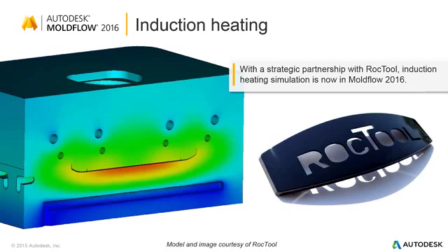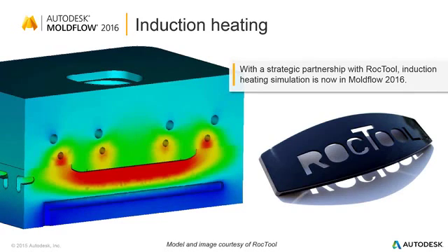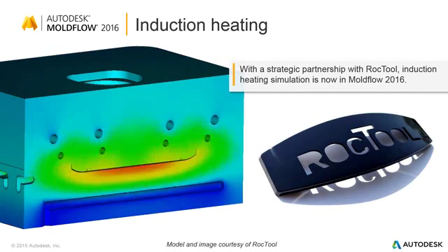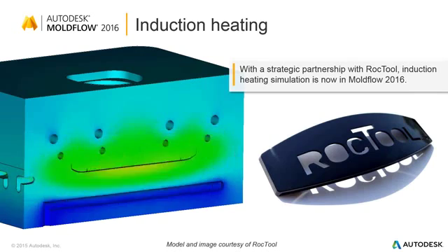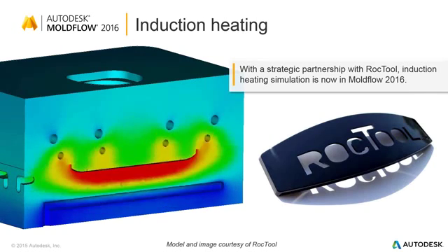The other benefit of the Rocktool technology, or the induction heating technology, is that the temperatures you can achieve with this are much higher than you can with, for instance, steam heating or heating cartridges. The company that brings it to market is a company in France called Rocktool, and they have started making really good inroads in the United States as well. They had a really good exhibition at the NPE, where I think two or three places were actually showing their technology live on the floor.